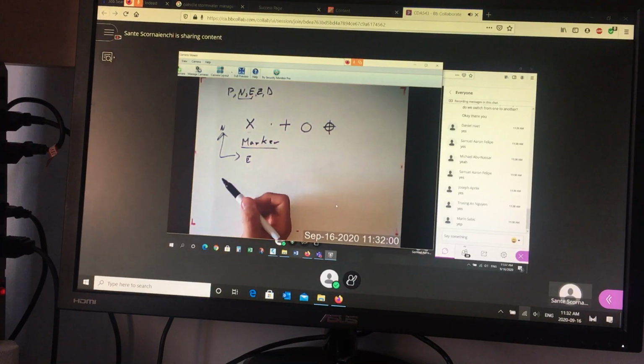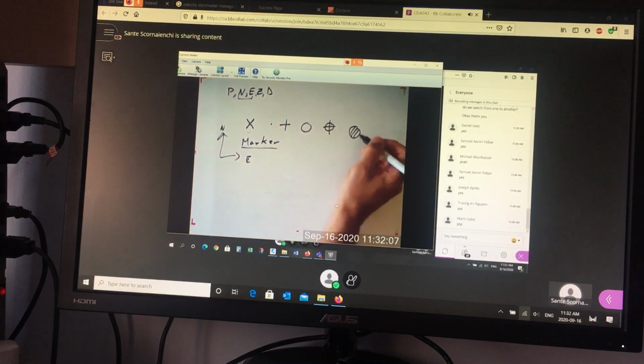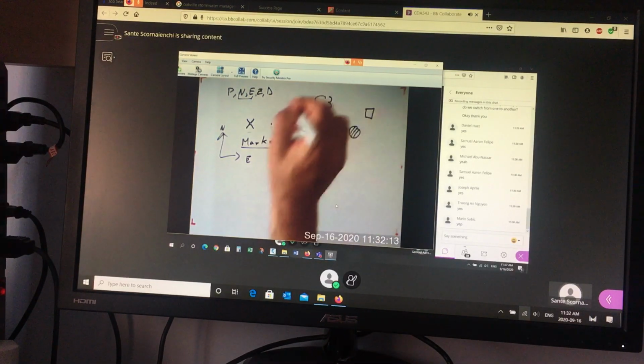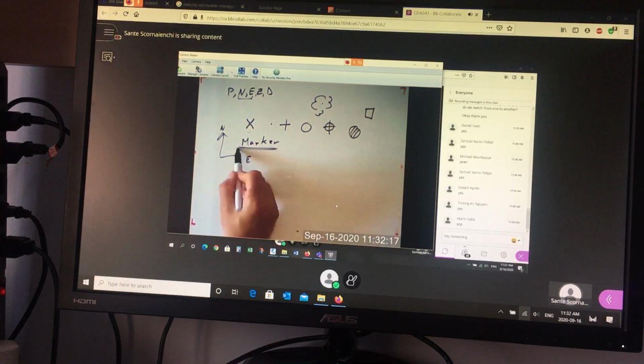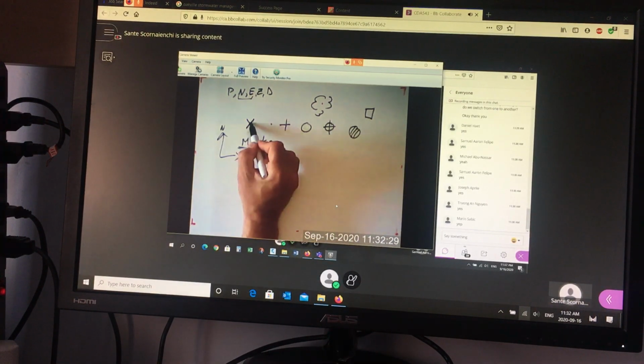Another thing you can use is blocks, right? So if you have a maintenance hole, you can have a block for a maintenance hole. You can have a block for a catch basin. You can have a block for a tree. That's the insertion point and so on. So you can actually use many, many things to create markers. What does the point look like, right? And if you use some clever point markers, you can do a lot of drafting for free. Okay? And I'll show you what that looks like. So that's the first thing, the style for the marker.